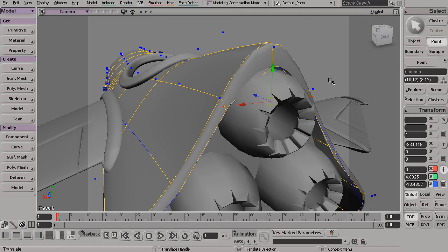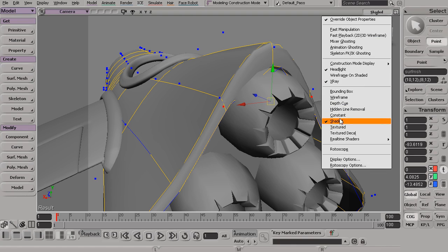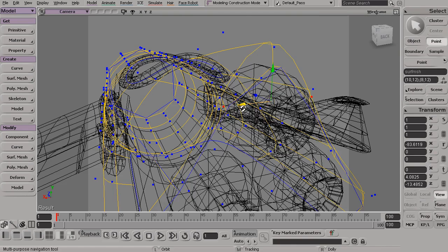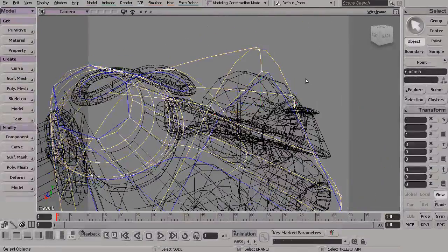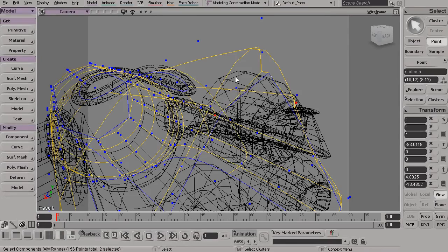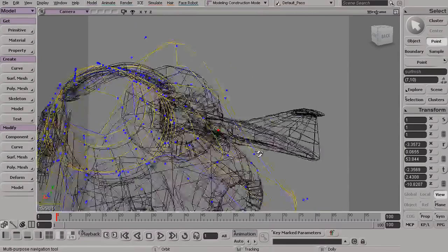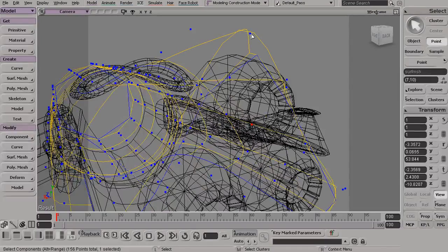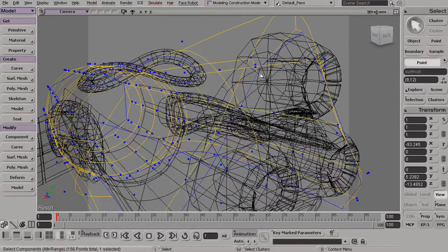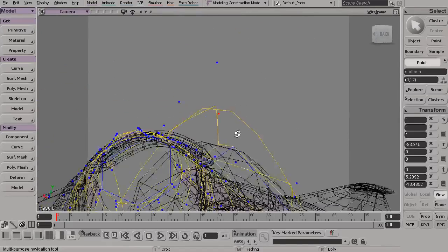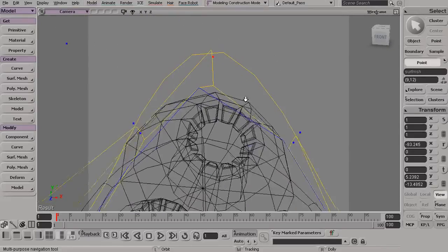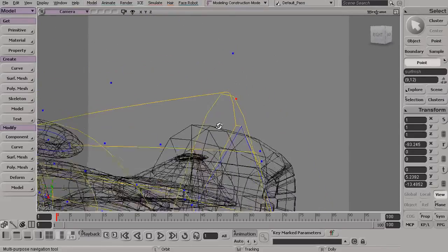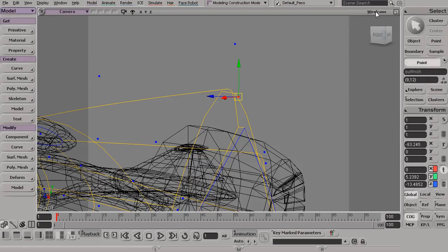And to make this a little bit easier to see, if I were to switch to my wireframe view, come in here and try to find that point that is hidden. Sometimes these can be a little bit tricky to find. So let's see if we can find that. So let's maybe try grabbing this point right up here. I'll press the F key on my keyboard to frame in on that. And what I'm looking for is the point that should be right below that. Actually, I think this is the point that I'm looking for. So let's actually grab that one.